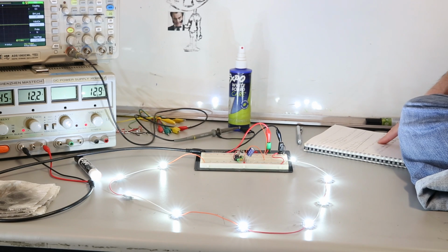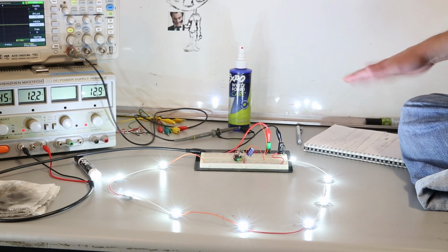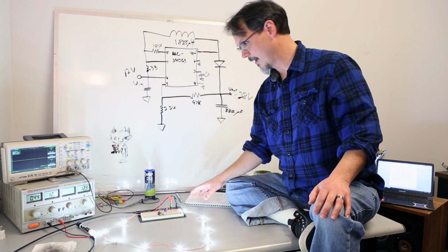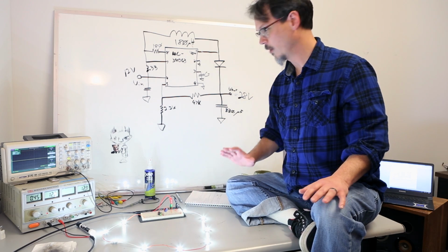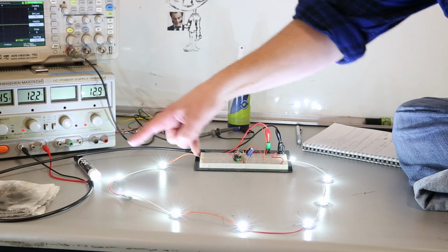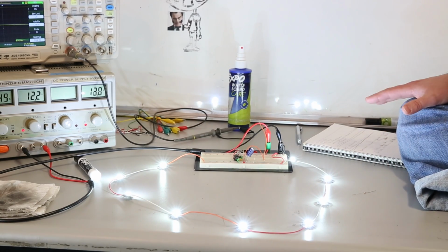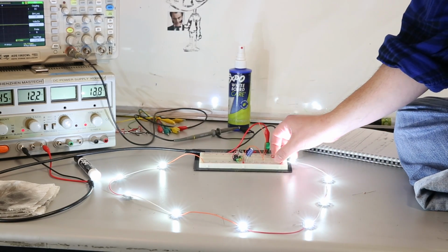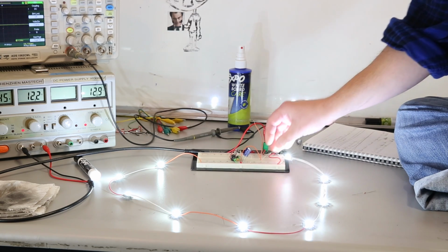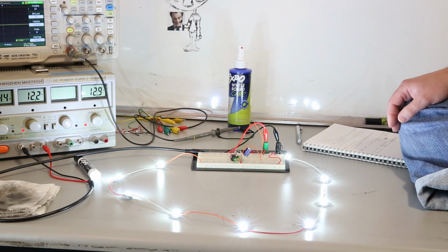They're actually running at about 157 milliamps. But this is just to prove that you can run this thing up. Works just like the datasheet says, more or less. But these add up to about 27 volts in series, and then I've got a little current limiting resistor, about 10 ohms there, that doesn't get too very warm, that limits it down to about 157 milliamps.